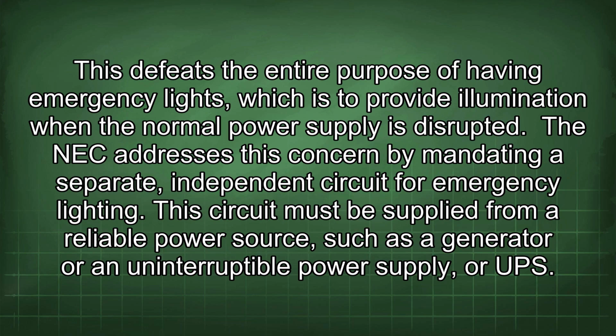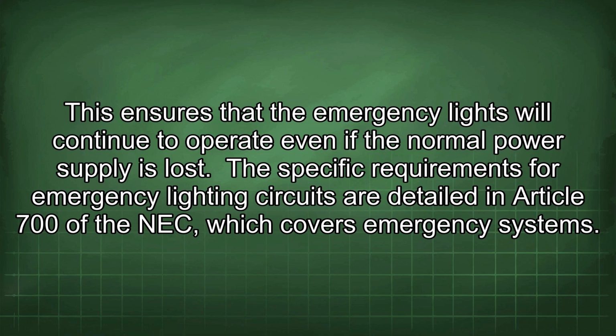This circuit must be supplied from a reliable power source, such as a generator or an uninterruptible power supply, or UPS. This ensures that the emergency lights will continue to operate even if the normal power supply is lost.